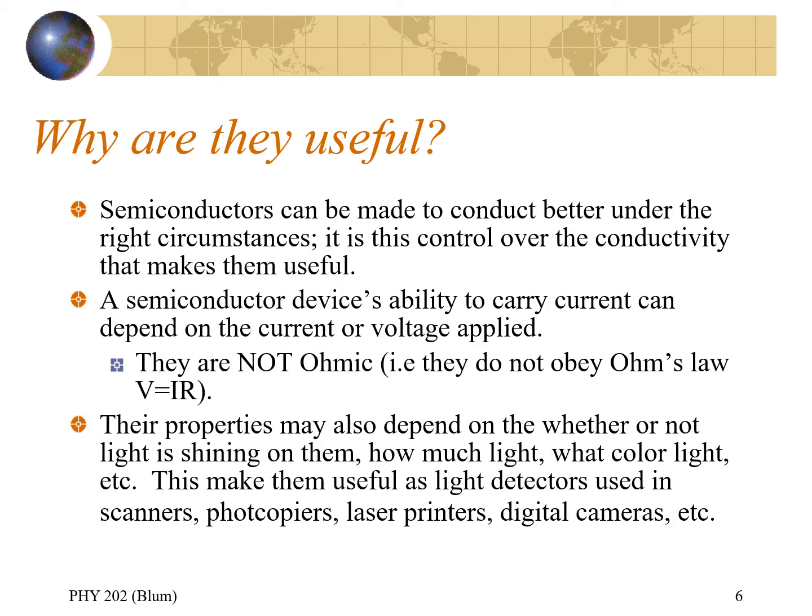If semiconductors are neither good conductors nor good insulators, then why are they useful? What makes them useful is that they can be manipulated, that a semiconductor can be made into a somewhat better conductor, and it's this control over their conductivity that makes them useful. Also, the semiconductor is not ohmic, it's not linear. So the resistance offered by the semiconductor can be changed, and this gives them their on-off quality that we can incorporate into our logic circuits.